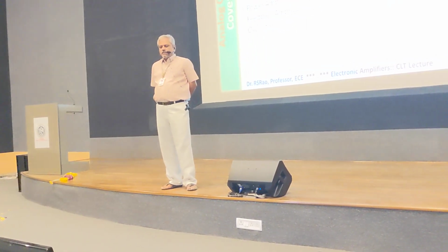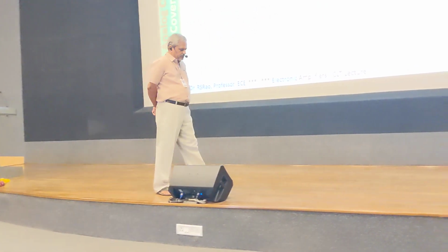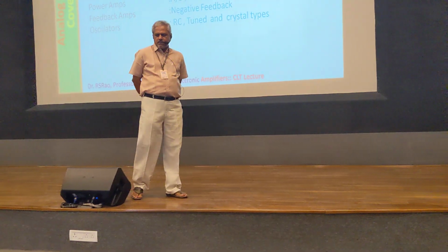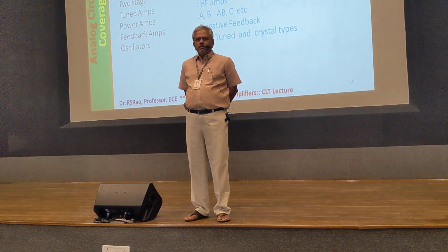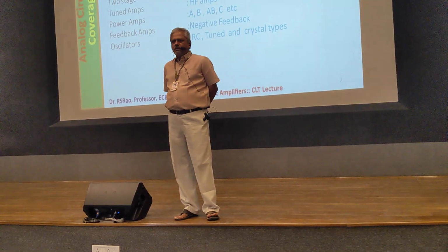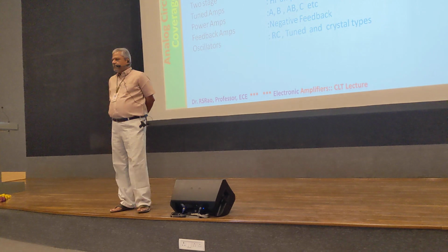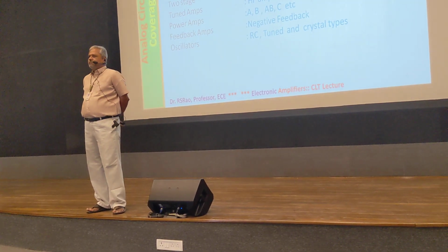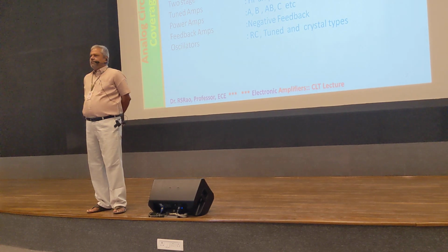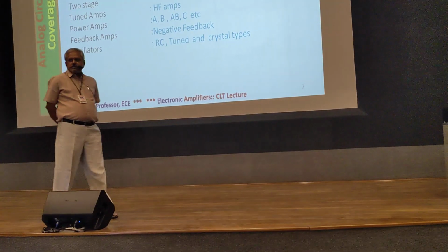In brief, CE offers a good amount of voltage gain, current gain, high input impedance, and high output impedance. So you can use it as a voltage amplifier, a current amplifier, and if you want, a power amplifier too. All good, performance is very good. Of course, it has one serious drawback. That drawback is a result of Miller's capacitance.